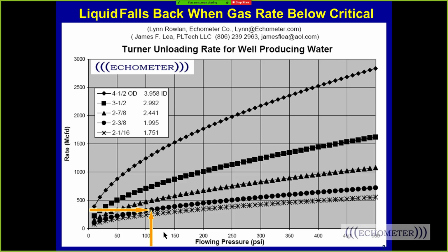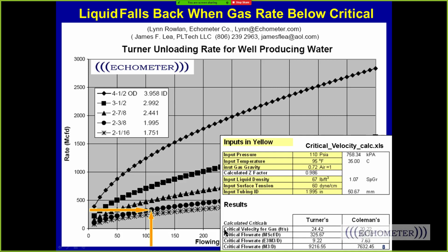And you need to intervene into the well and add some type of artificial lift. Now, this is the spreadsheet. On the spreadsheet, I've included this critical velocity calculator, but I also included a correction for hole angle, because if you get below the kickoff point, you're typically not vertical, and Turner was done on vertical wells, and these are the calculations for a vertical well.